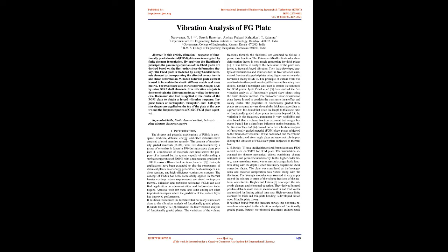Impulse forces of rectangular, triangular, and half-cycle sine shapes are applied on the top of the plate at the center, and the response spectra of C-SiC FGM plate is plotted. Keywords: FGMs, finite element method, heterosis plate element, response spectra.